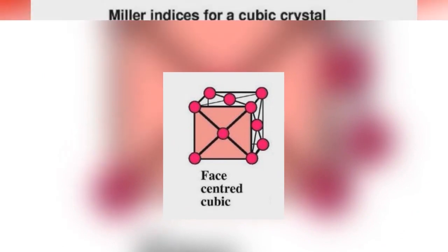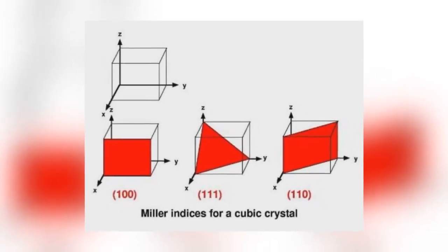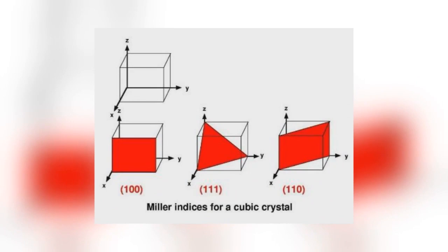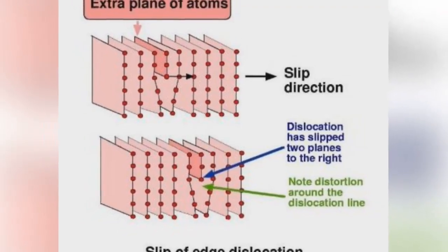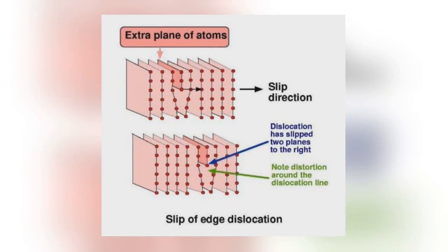Aluminium crystals can change shape through plastic deformation, which occurs by the slip of atoms when sufficient force is applied. Slip primarily occurs on 1-1-1 planes, facilitated by the movement of dislocations, which are boundaries of extra planes of atoms. This localized slip requires less energy.